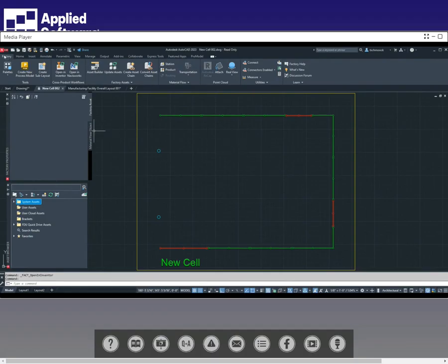So as you can see up here in my factory, I have the factory tab, and I can do my automatically converting over to Inventor. And then here are my factory asset tools. If I had an AutoCAD file or an Inventor file, and this can work on models, part models, or assembly models, you can turn them into the asset. When I drop one in, I'll show you that the difference is you can add parameters and you can adjust them a little bit more. So I'll talk about it, but I won't do it in here.